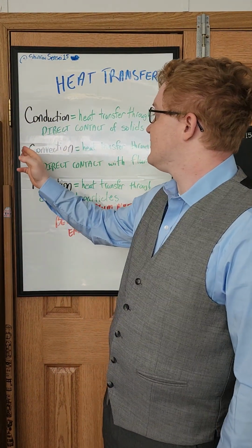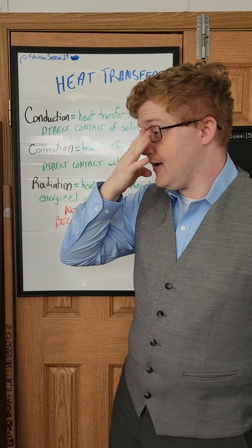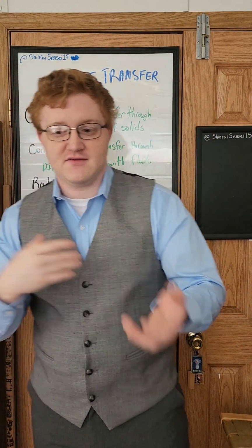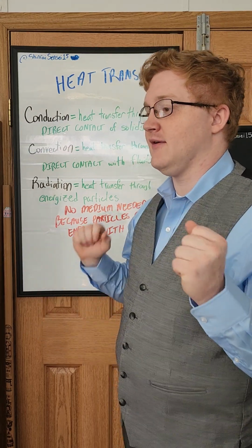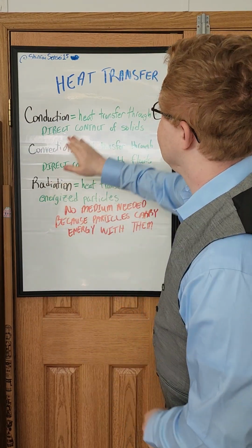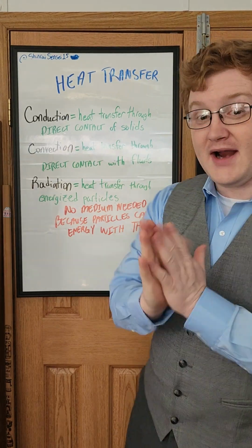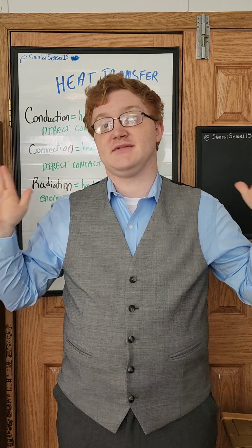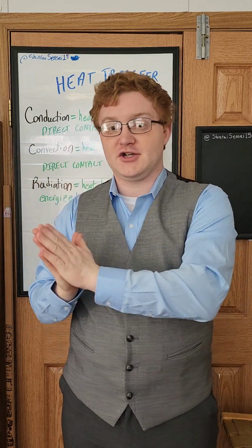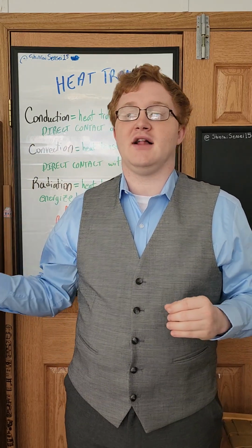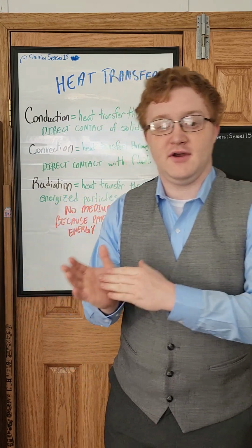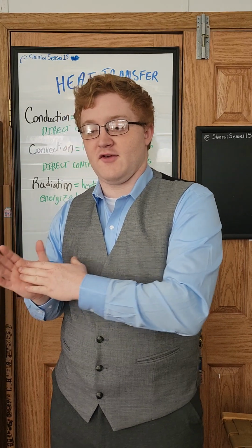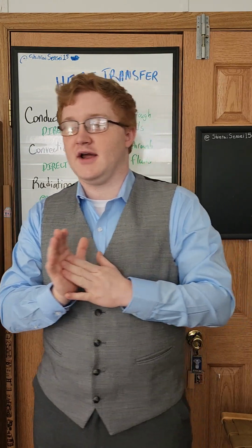There's conduction, convection, and radiation, right? And I've kind of simplified the definitions of each one in ways that are easy to understand. Conduction is heat transfer through direct contact with solids. So it's not necessarily that it has to be two solids touching each other for it to be conduction. It can be a solid in contact with a fluid, where the fluid is receiving conduction from the solid, right?